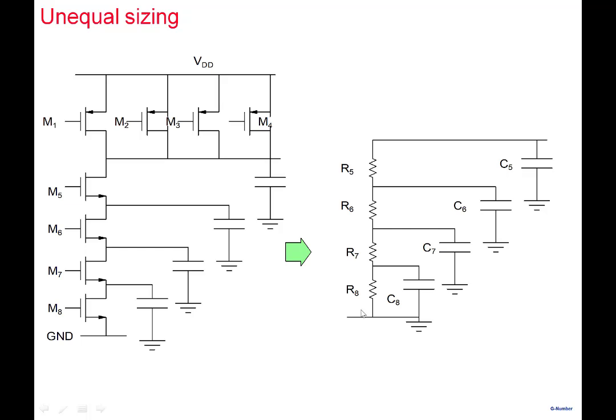So maybe if you had one transistor to increase the size, or in order of importance, maybe you would try to do it in this particular manner here. M8, M7, M6, M5. If you had to make it unequal, maybe make the size of M8 the largest, whatever largest size you can accommodate, then you make the size M7, then you make M6, and then you make M5 here. All right, so maybe this sort of makes sense in terms of the unequal sizing here.